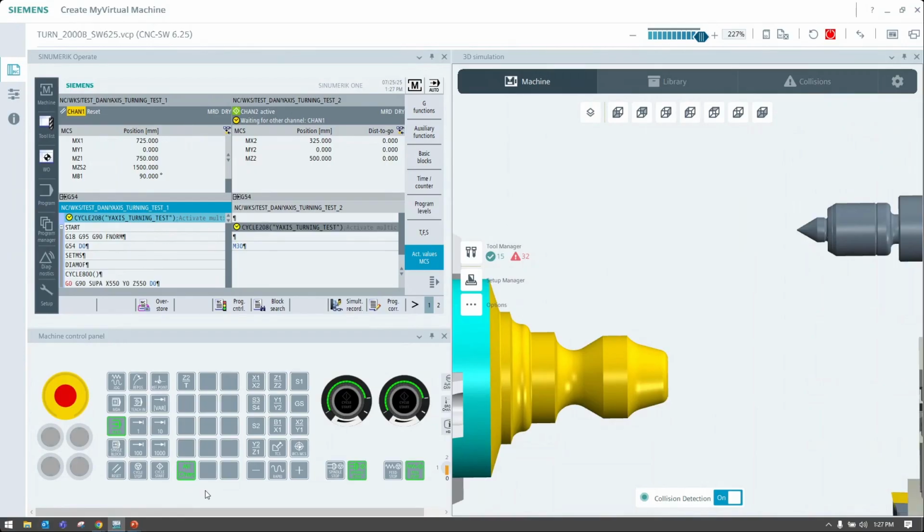So that's definitely going to be huge. In the world of using Y-axis turning, I think it's still going to be wait and see if there are going to be turret-based tools, if you have enough swing in the Y-axis for a lathe, because some lathes have Y-axis. I think that could warrant some of this, and I think it could be huge because your force is going towards the turret, right, through the turret.